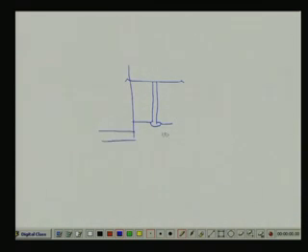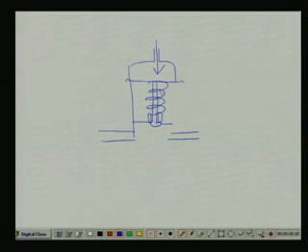What is this? We have seen that I have a diaphragm, okay. So, this valve sits on a seat, right. There is an inlet, an outlet, the pressure is coming and there is a spring action, there is a plug here for packing, okay, this is a packing. So, if the pressure comes, the stem will move up and down and it will control the position of the plug in the seat, thereby controlling the flow of the liquids.